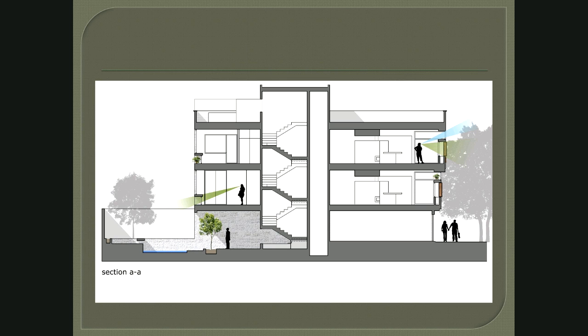So here's a section of a building, and this one tells us a lot. We've got floor plans here, but we've also got this little cutout courtyard area at the bottom, and you can see how the stairs go in and where they land for each side. And this one's also showing where someone's got views out. And here it shows how the sun's coming in. So you can use a section to show how the sun impacts your building, how views are used, and then again, how spaces are arranged so that you have a better understanding of how it's put together.